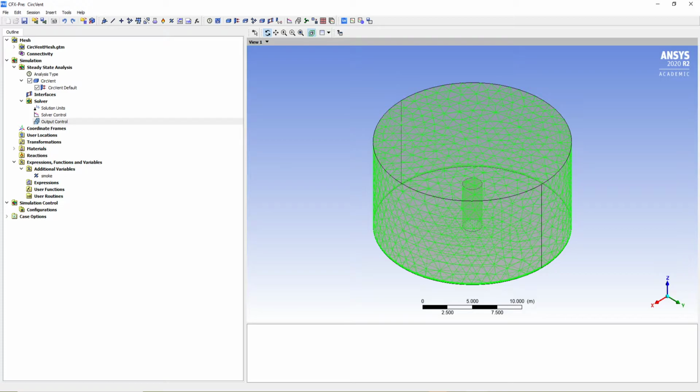However, the length scale values produced by the default intensity and the autocompute length scale that we used before in our lectures are usually options for turbulence based on the inlet size. They are appropriate for internal flow problems, particularly cylindrical pipes. So in general, you need to set the turbulence intensity and length scale explicitly for large inlets, especially external flow problems such as this one. If you don't know the value for the length scale, you can use a length scale based on a typical length of the object the fluid is flowing over. In this case, we're going to choose a turbulence length scale that is 1/10 of the diameter of the vent. You'll understand this better when I show you where these values are going to be put.